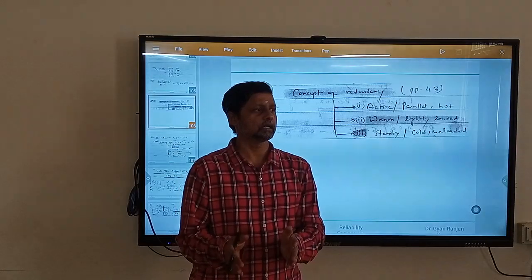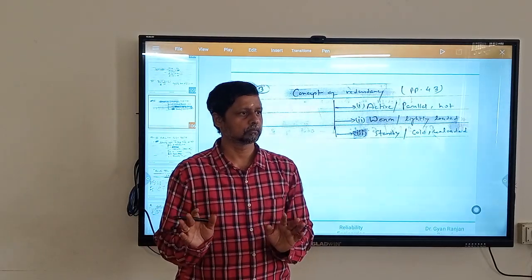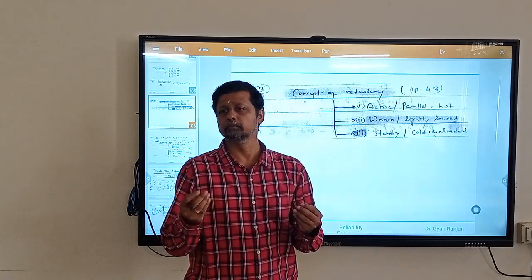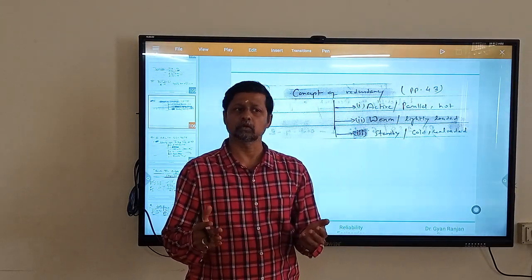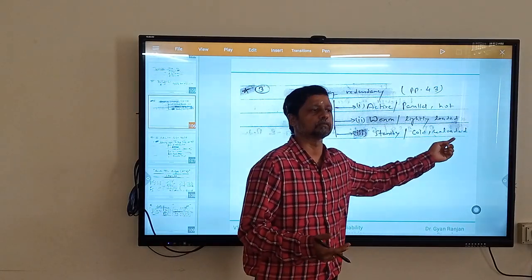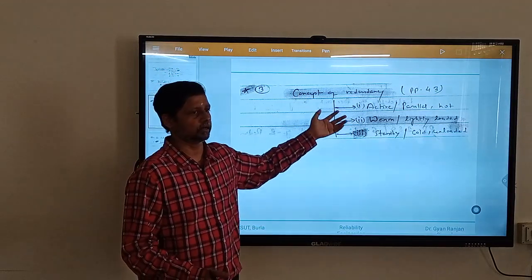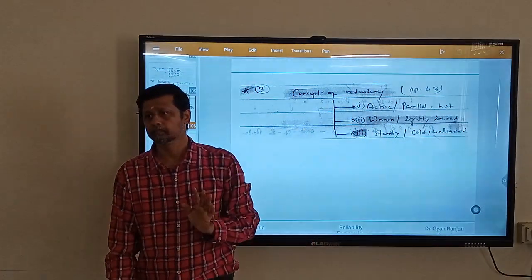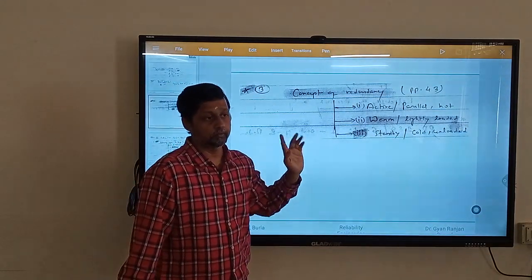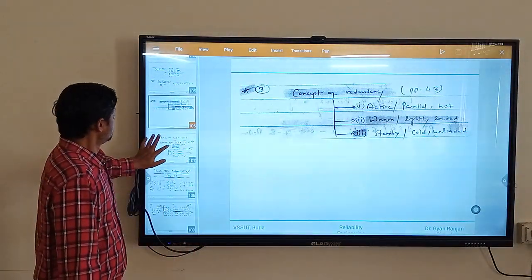Okay, earlier the job was done by this bench. Now you have given me an instruction, so I will start working. But of course, during this exchange of information, it will take some time. It may be a few minutes also. If your application is not hampered by this performance issue or compromise, go ahead, because that is the most cost-effective among the three. Understand? But the mathematics working behind it, whenever you talk about redundancy, will remain the same. Clear? So from the reliability aspect, you do not experience any difference. If you judge it from the automation aspect, then there is a difference. Clear?